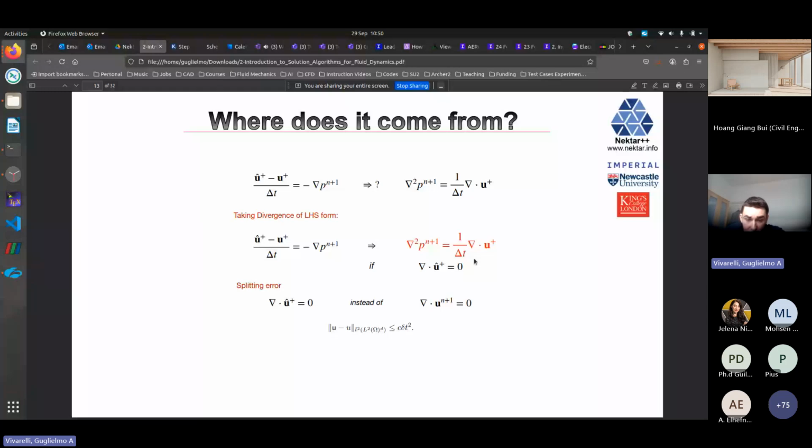What happens is this is proportional to the time step squared. So the smaller the time step, which in any case is governed by the explicit part of the splitting scheme, so the convective terms. Because it's explicit, it's still going to drive down the time step and limit you. So as a rule of thumb, it's generally okay. And then, of course, as you refine your time step more and more, you're going to get less and less error. But nonetheless, it's worked very, very well for us.